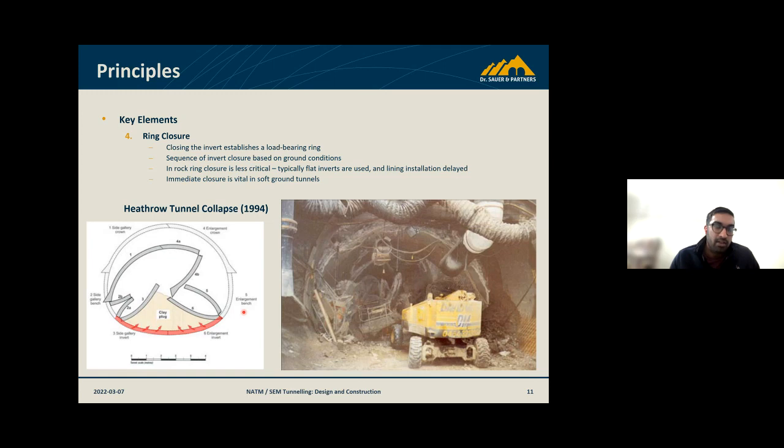And that's where you get that failure, whereby you have these stresses coming down, redistributing around the tunnels, and as they're pushing inwards, that invert location becomes very, very important to construct properly. So if that hasn't been done properly, or if there's a connection there that wasn't looked at carefully, or if you end up driving too many of the top headings first and not coming down and closing that ring, then you end up with a case where instability can occur and you get this invert heave.